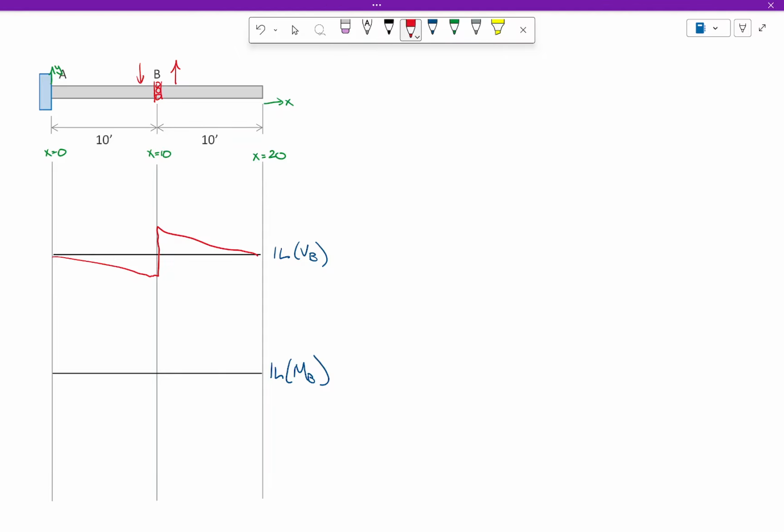But let's also just think about this, okay? I am drawing the influence line for the shear right there. What is the shear right here when the load is here? What is the shear in the diving board when the load is present right there? Zero. I propose that the influence line needs to be 0 throughout this entire region.